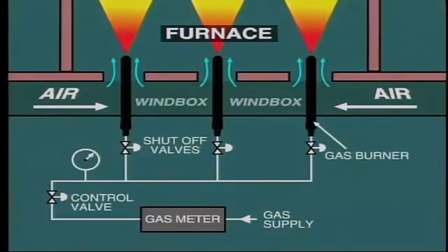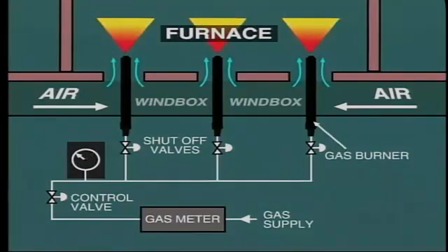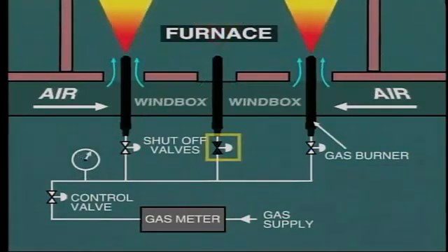Control of heat input to the natural gas boiler is similar to oil firing. That is, the flow of fuel to the burners can be adjusted by control of the fuel supply valve, at least over a certain pressure range. However, if the fuel supply is allowed to fall too low, we may get unstable combustion. In this situation, it's necessary to shut down one or more burners completely, and so raise the supply pressure to